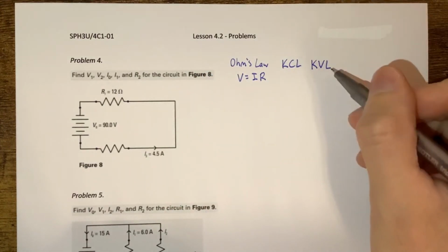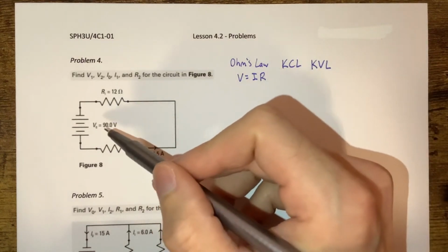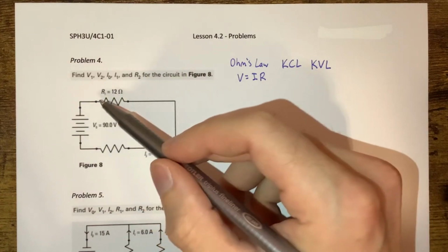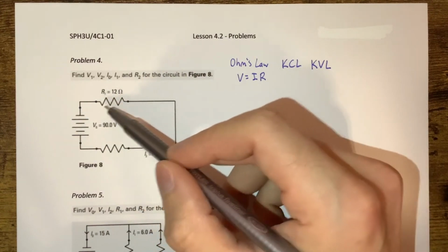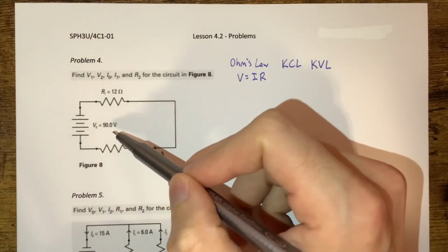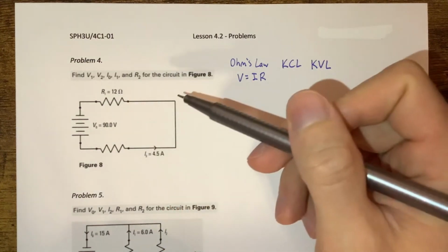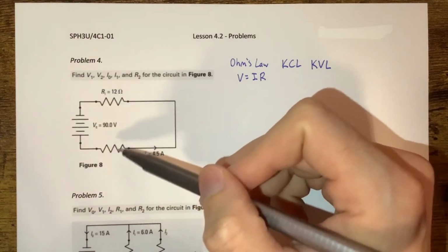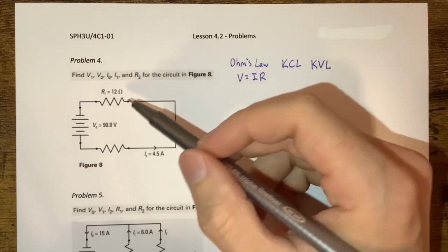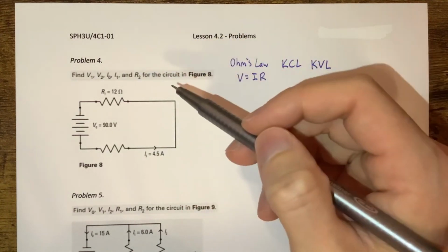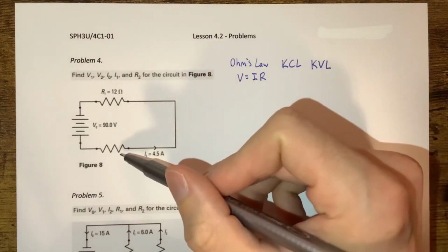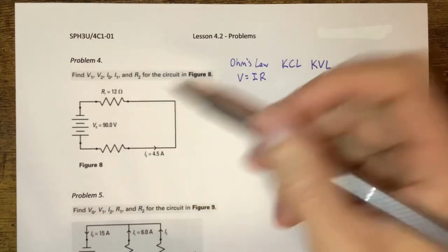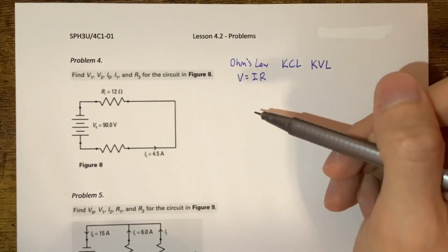And essentially what this law is saying is that if we start with 90 volts here, right? The sum of all the voltage drops across these loads, like this resistor here, has to equal 90. Okay, so we haven't done it yet here, but if we had one resistor here, one here, let's say hypothetically this one had a voltage drop of 45, and then this one would also have to be 45, because 45 and 45 gives you 90. But we're going to calculate that exactly for this one here.